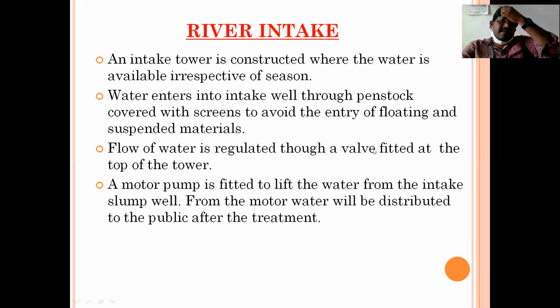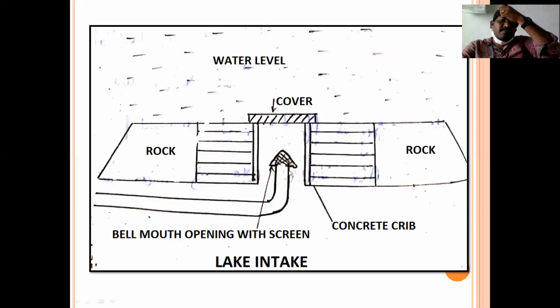For lake intakes also we observe this type of opening, the bell mouth, and this bell mouth is covered with screens. What is the purpose of these screens? Just to avoid the entry of soil particles. This entire structure is covered by a cover, or else a closed type structure.